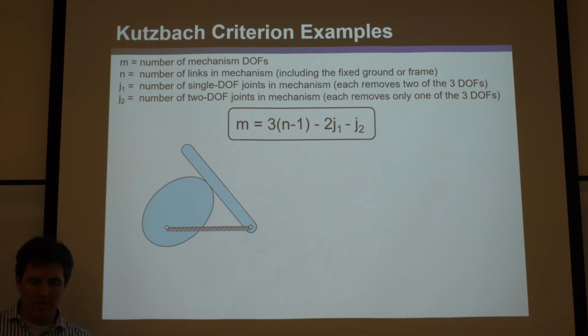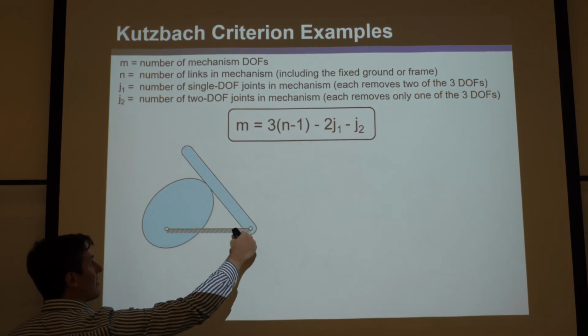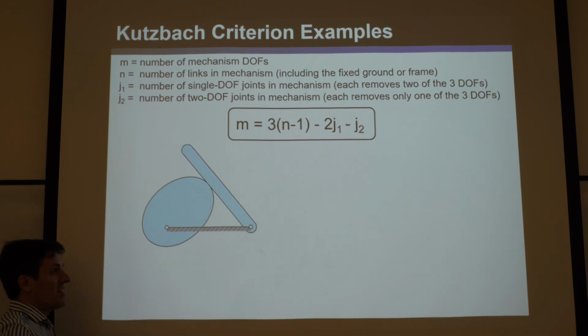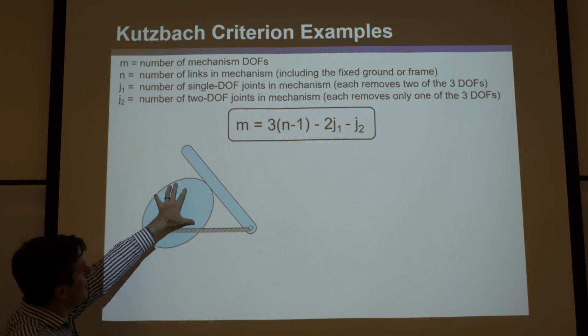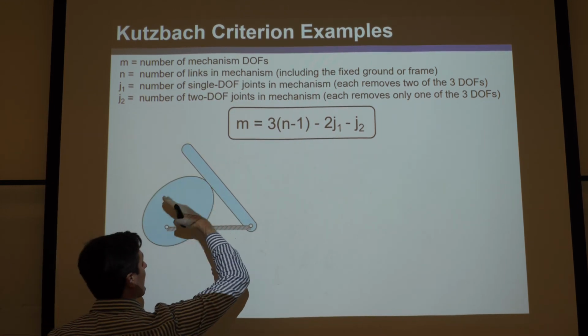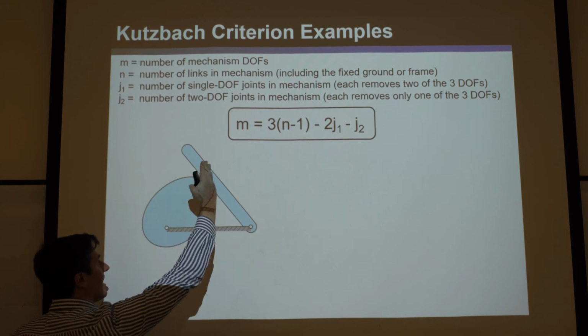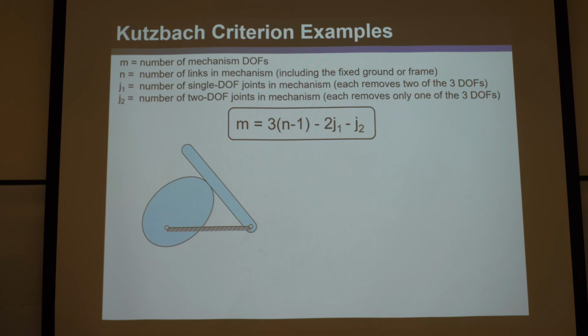That's one critical thing for the definition of a mechanism. It's a closed kinematic chain. You bet it's closed. And can it move? Yes, it can. You can imagine if I put a motor on this and rotated this egg around, that link would kind of ride up and down it as it moves. So it can move, and so yes, it's a mechanism.